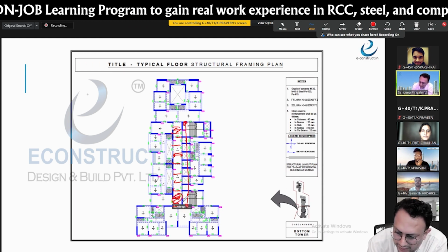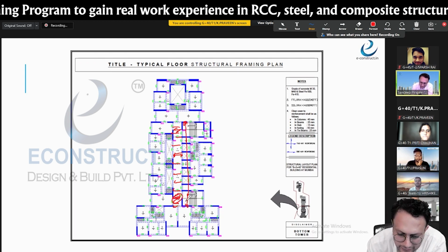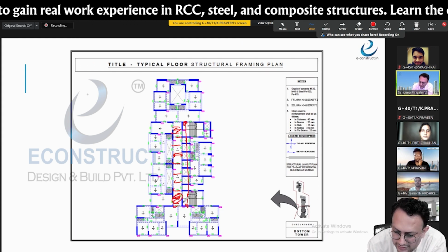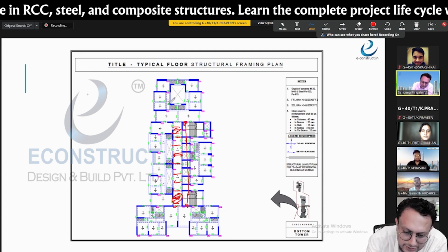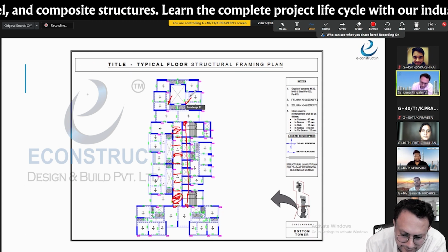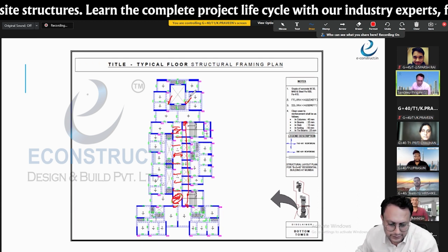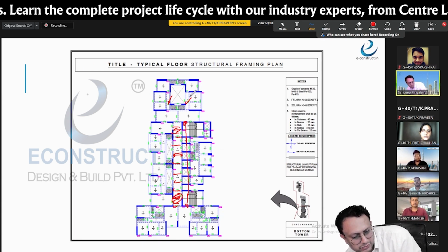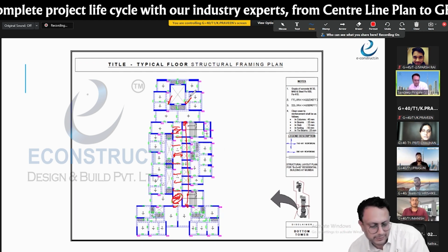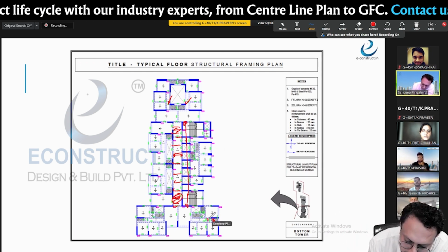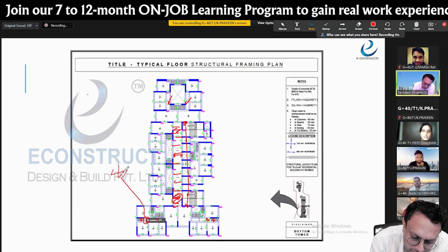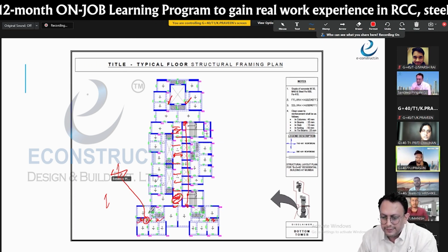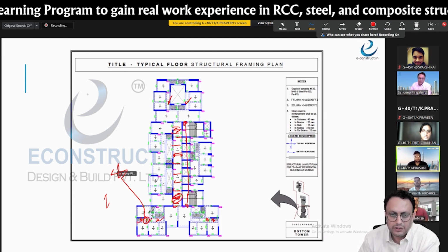I know that this can be two-way, but how much saving are you going to make? Hardly anything anyway. Got it? So these are small tips I would suggest, which are to be given by you only. It will be helpful to the bar bender to cut the bars. Similarly here also, one way. Even though this slab can be two-way because of Ly by Lx, we are giving it one way just to make it easy for the bar bender. Got it?